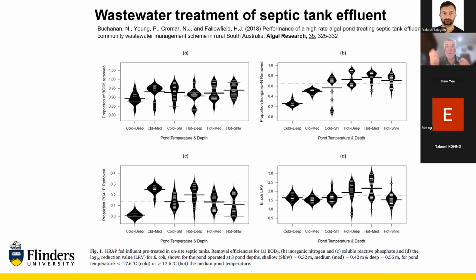And one of the points we looked at was we could say, okay, overall, there was very little difference in the treatment to remove BOD by changing depth, because the median values of the data within these violin plots were much the same. The only case was maybe in a deep pond, when it was cold, the removal was slightly less. But we're talking here the difference between 90% and 95%.